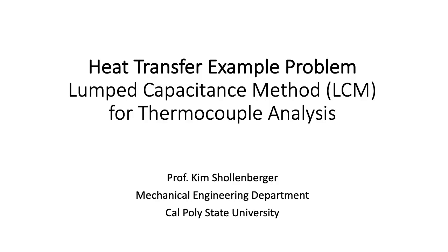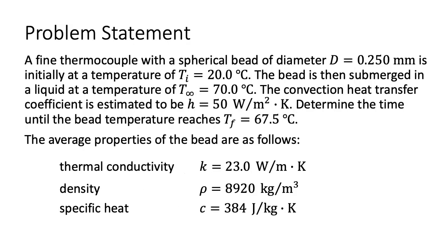ME350 example problem for the lumped capacitance method for thermocouple analysis. A fine thermocouple with a spherical bead with a diameter of 0.025 millimeters is initially at a temperature of 20 degrees Celsius. The bead is then submerged in a liquid at a temperature of 70 degrees Celsius.